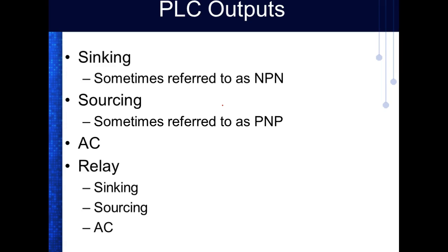What's nice about relay outputs is you wire them the way you want. And every output usually has its own common. So you could have output 0 sourcing, you could have output 1 sinking, you could have output 3 running AC, right? You understand? So that's what's really nice about relay outputs, is you're not tied to sinking and sourcing on the ports. But you hear them click.